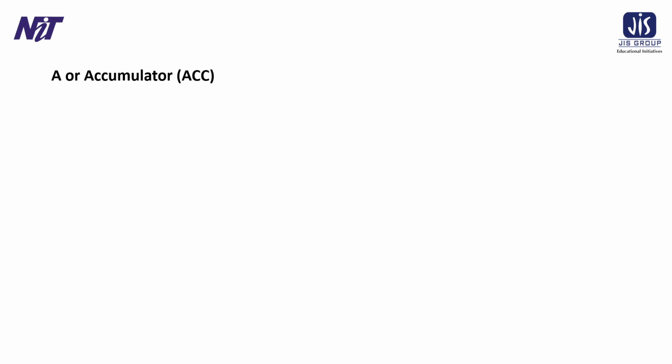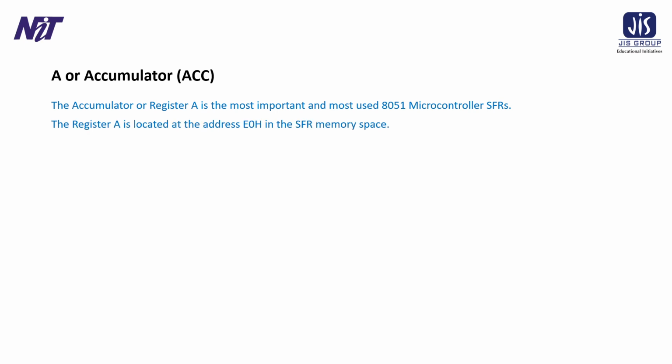First, A or accumulator. The accumulator, register A, is the most important and most used of the 8051 microcontroller SFRs. Register A is located at the address E0H. The accumulator is used to hold the data for almost all ALU operations.